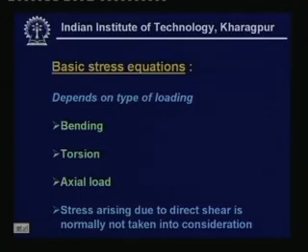Before going to the basic stress equations, if you recapitulate the very first or second slide, when we talk about a shaft, we understand it is acted upon by bending. Suppose onto a bearing support a load is there, then that is a bending. A torsion, that means when it is transmitting power, and there are situations where you can also have axial loads present onto the shaft.